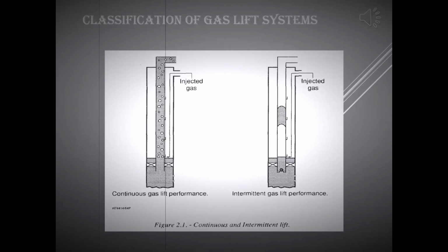Intermittent gas lift. It consists of injecting high-pressure gas into the tubing, at sufficient volume and pressure to lift the fluid head, accumulated above the valve, to the surface with maximum velocity for a short period, in order to minimize aeration and fluid fall back.